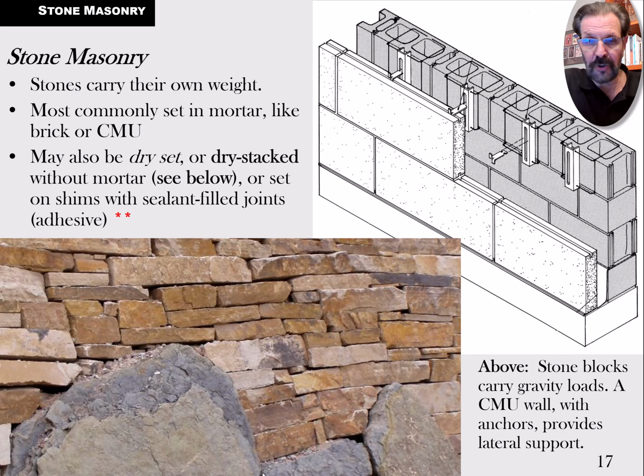That's what I've normally seen in this, where they've had cut stone that is stacked. It's got grooves, and besides its weight and the grooves, it's held with clips that are laid into the mortar of the concrete block wall, and those clips come off to hold this stone wall. So it's kind of physically held in place.